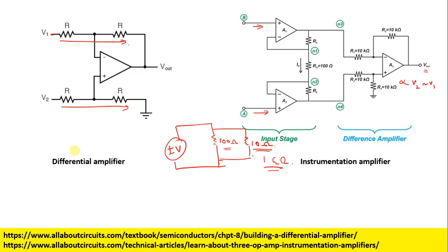So it is finite. Since this resistance is finite, that means the input impedance is finite, and hence there would be a loading effect, and due to that you will be losing the current. And in the case of biopotential signals, our biopotential is either in the microvolt range or in the millivolt range.